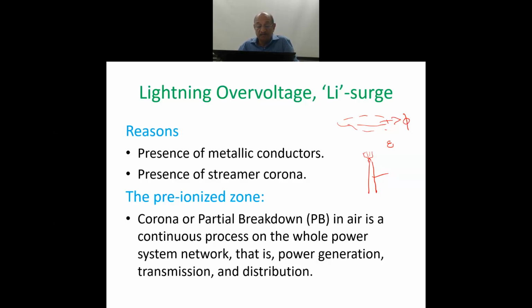Corona may happen there. The corona at such locations under sufficient electric field density develops in the form of a streamer, we call it. This streamer develops at the metal on the ground. This is all on the ground.